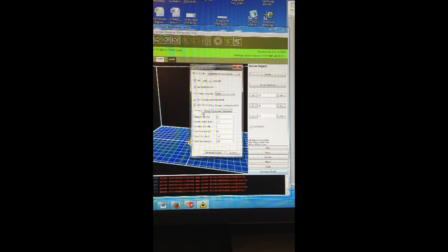Next, we will go to the Settings tab. The printer guide will run through these specific settings. Object Info references the amount of filament that is used while laying out the material. Layer height is recommended to be 0.27. Number of shells is the wall thickness, should be 1.